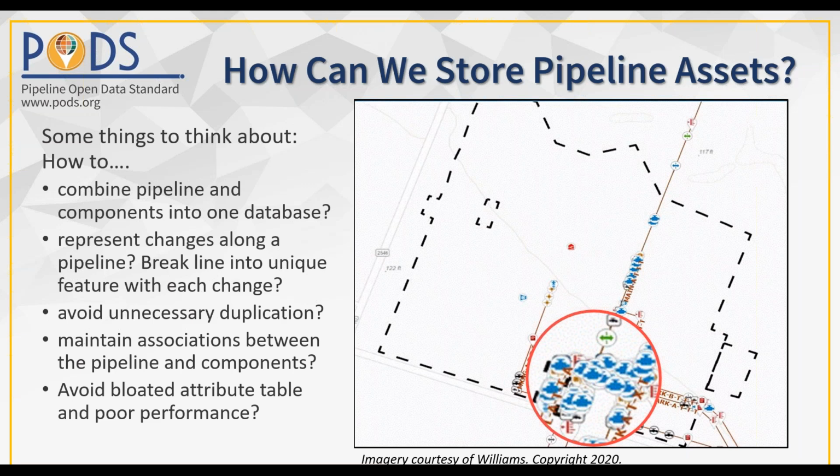Another consideration is the regulatory and industry best practice that dictate different rules for managing certain types of pipeline attributes. So for example, if a pipeline manufacturer was unknown and then it was updated to USS, for example, the edit is made without creating a brand new record in the pipeline layer. However, when a diameter changes, the original pipeline record is not updated. Instead, a new record is created in order to maintain the pipeline history.